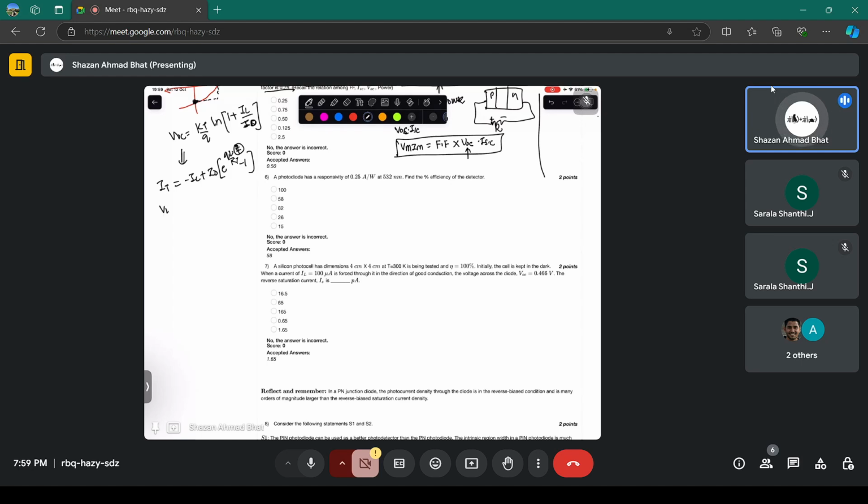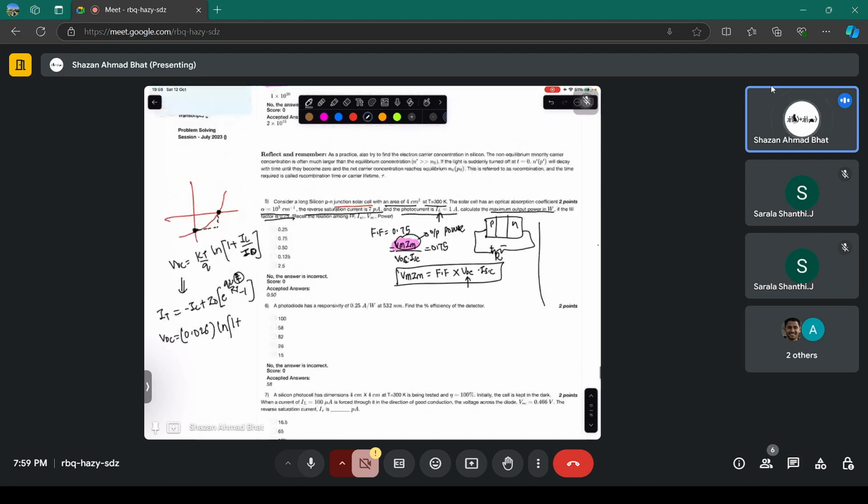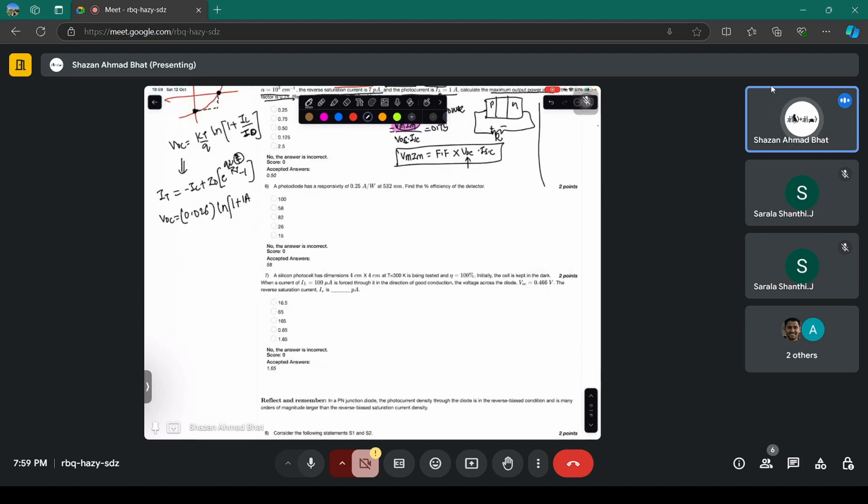So now open circuit voltage you can compute. It is mentioned that it's at 300 Kelvin, which is room temperature. So you can take kT as 0.026, and I guess other things are given. So ln of 1 plus how much is IL? It's 1 amp. Okay, yes, it's 1 amp divided by 7 picoamps. You see that this value is huge.